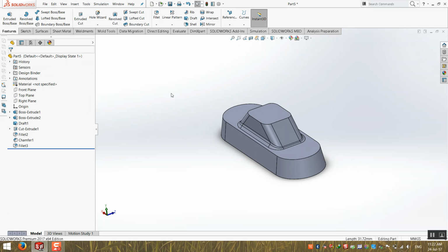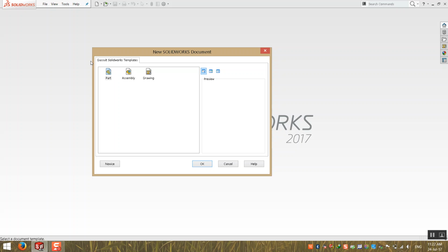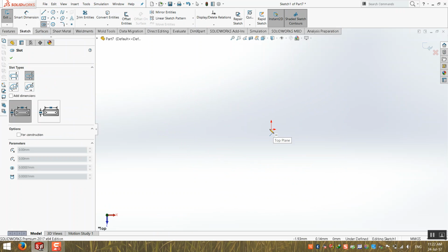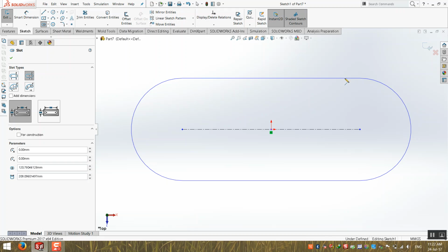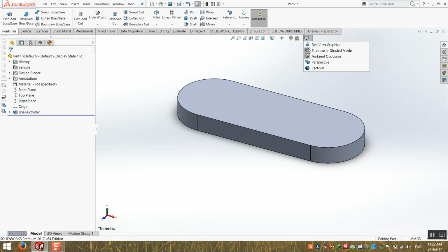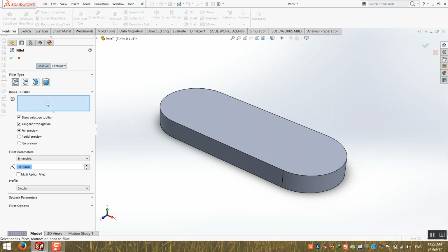Let's see together in a new model. Extrude. Now, when you get a fillet, 5 for example, and select this edge, just 5. All edges here are 5. Yes? Now, we will make something like a chamfer called asymmetric.